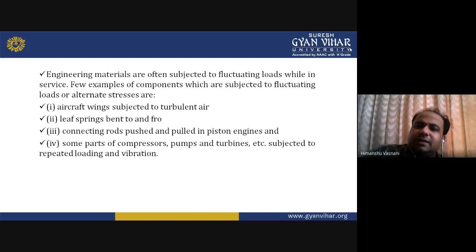Now, engineering materials are often subjected to fluctuating loads while in service. Obviously, in service, it will lead to some kind of fluctuating loads. A few examples of components subject to fluctuating loads are aircraft wings due to turbulent air, leaf springs moving to and fro, connecting rods pushed and pulled in a piston engine, and some parts of compressors, pumps and turbines due to repeated loading and vibration.